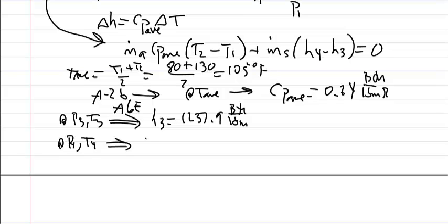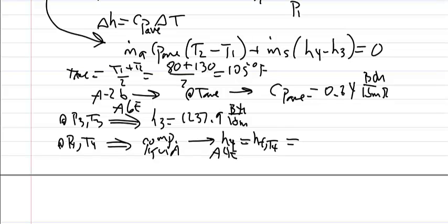So whenever we have a compressed liquid, we either use the compressed liquid tables, but the compressed liquid tables provided in our textbook are very poor, and we don't have an entry at this low of a pressure, so our only choice for compressed liquid is to make the usual assumption, which is that it's approximately equal to that of the saturated liquid, hf, at the same temperature, not pressure, at the same temperature. So we're going to actually have to go into our temperature table, which is table A4E, at the appropriate 212 degrees Fahrenheit, and we would find that the enthalpy is 180.21 BTUs per pound mass.